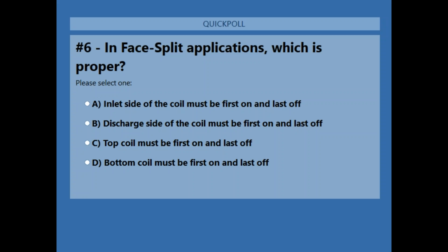What's kind of replaced hot gas bypass is what's called a minimum load valve, which is essentially doing the same thing. We're introducing hot gas into the evaporative section. So it does the same thing, different name. We accomplish it in different ways now. On the screw chillers, it's a solenoid valve that opens up, and we inject the hot gas right into the evaporator barrel.